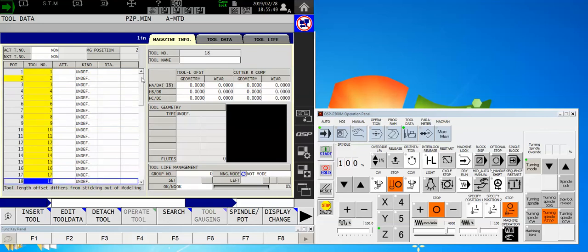Just simply when it comes time to set a specific tool, I'll call that up, put it in the spindle, and touch it off on my stylus if I have a tool setter. Or if I have a presetter, I could highlight, call up the offset category, and just set my tool value to whatever the known preset value is. In this case, let's just say this is a 4-inch tool, and now, boom, I've got a population in my tool offset library. That is all I need to do to get the machine to function.